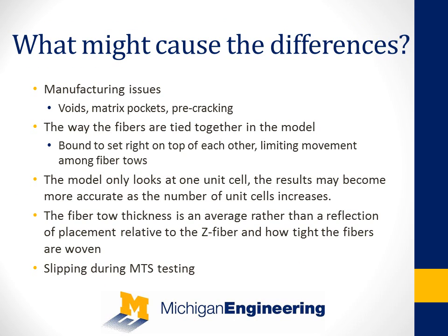So what might cause the differences? Well, manufacturing issues. The model doesn't take into account any voids or matrix pockets or pre-cracking that typically occurs around the voids. So this may either underestimate or overestimate because it's assuming a perfect architecture.